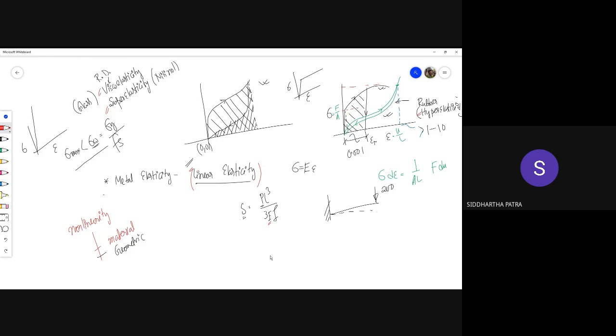Okay. With all of these linearity in consideration, you see there is a geometric property over here as well, I, moment of inertia, which could be changing due to lateral compression of the beam. But we consider the strain to be so small that the lateral compression is even smaller, and then we didn't consider the change in cross section. So when you do not consider any of these, then you have the linear finite element method.